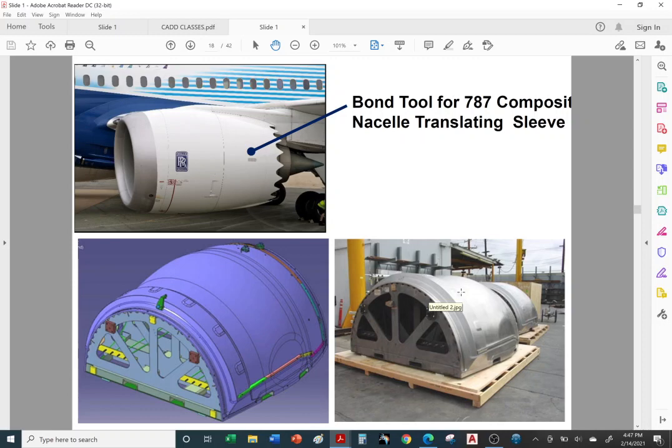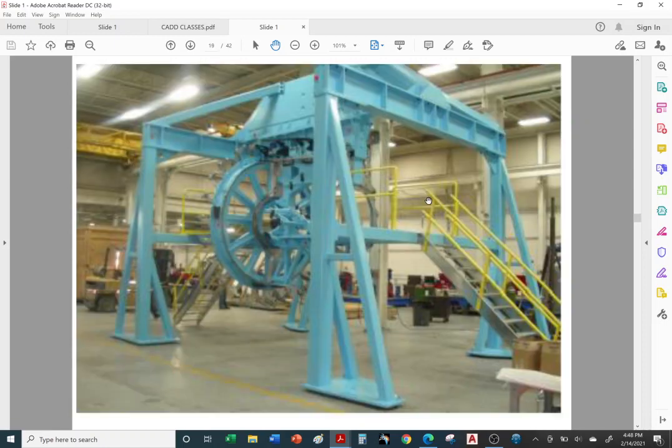So when you get on an airplane and you walk on the floor panels, those are most likely made out of carbon fiber. So a carbon fiber sheet on top, one on the bottom, and I think it's aluminum honeycomb inside to keep it lightweight, but yet make it stiff so it can handle the weight. Okay, so again, tool design makes the parts of the aircraft. It can be a mold or it can be something to assemble.